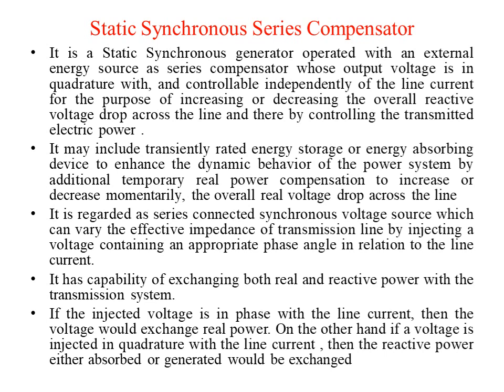If the injected voltage is in phase with the line current, then the voltage will exchange real power. On the other hand, if the voltage is injected in quadrature with the line current, then reactive power, either absorbed or generated, will be exchanged.